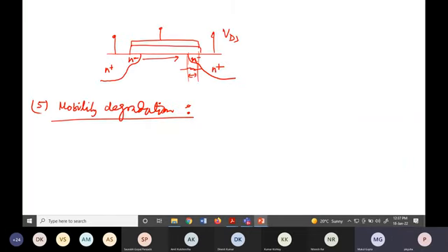So this mobility degradation, why it takes place is the reason I just mentioned in the previous point, number 4. This mobility degradation occurs because, as I said, we can't reduce VGS as aggressively. If we don't reduce voltage at the gate, the carriers will be very close to the gate silicon interface, because the electric field they feel from the gate side is quite a lot.